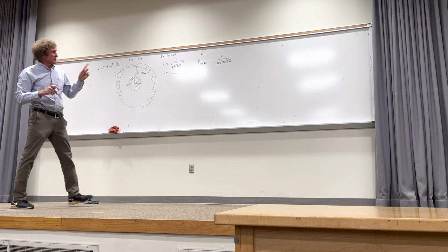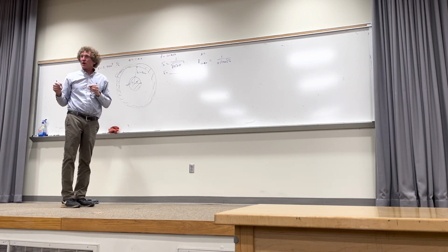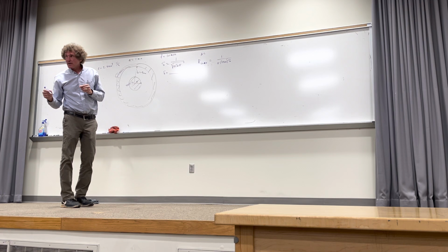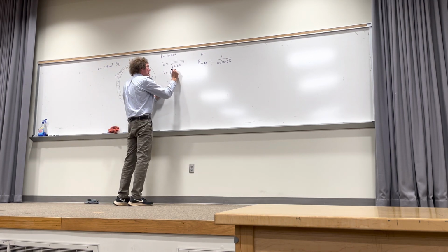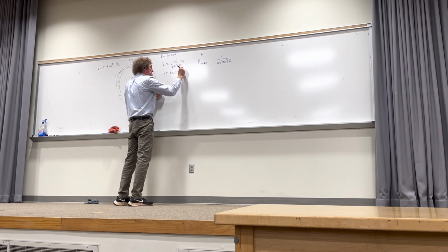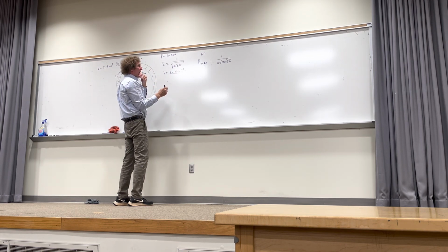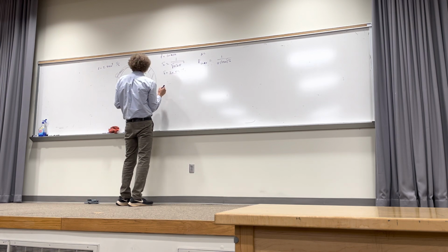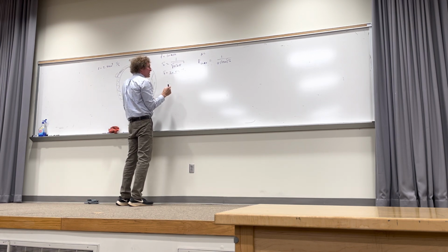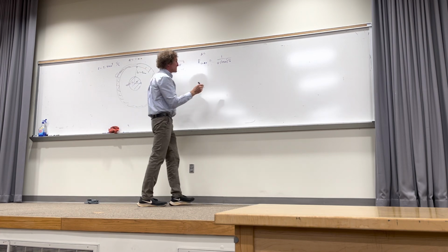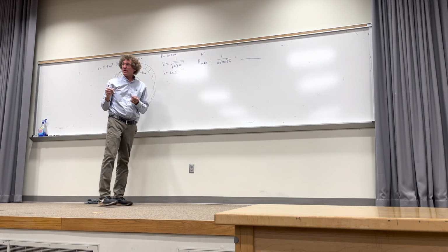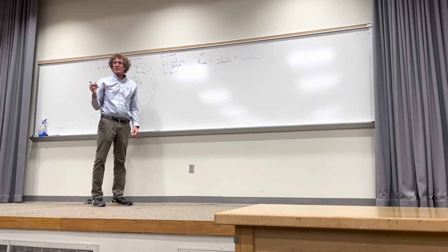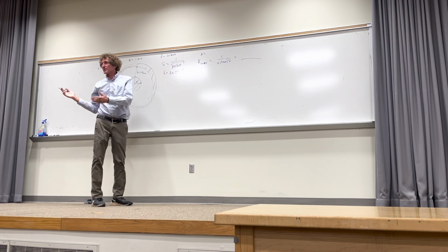Okay, so what do we get for the skin depth? 20.89 micrometers. 2.89? 20.89. Oh, sorry. Micrometers. 20.89 times 10 to the minus 6 meters, okay? For this one, a was 1 millimeter. So you can give me this value, right? That's for the core. I've got the calculation done. You can look if you've got access to it. Just tell me. Or you can calculate, make sure it's right.